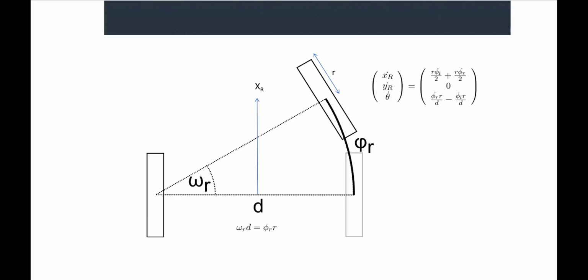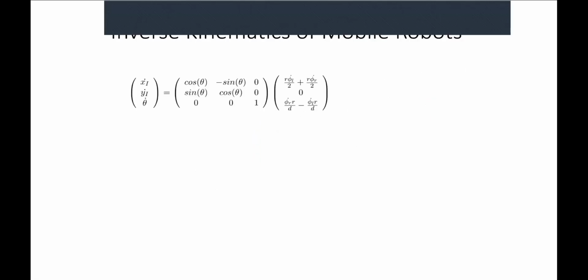So if we take these forward kinematics equations, we can set this up. This is the same thing we've been looking at for the past couple of weeks. The x, y, and theta changes in my inertial frame are the rotation matrix multiplied by my x, y, and theta displacements. We can rewrite this, using psi as my robot's pose. The change in my robot's pose in the inertial frame, my external world map frame, is equal to this transform multiplied by the change in my robot's local frame. From my robot's perspective, I go through this transform, and then I get the change from my global perspective.